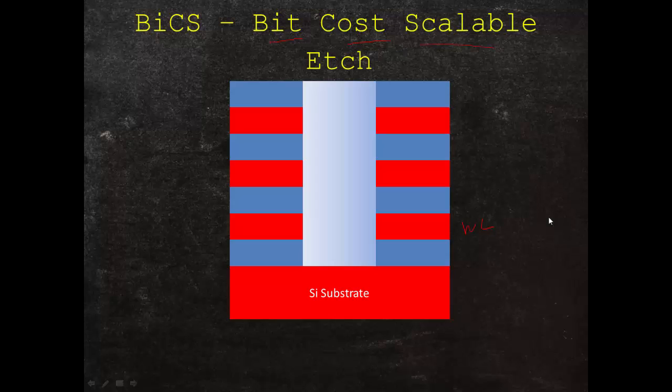So a process note: these are long trenches and they're difficult to manufacture. But only one mask is needed to produce this entire array of holes, and that brings the litho cost down. So we have a pro and a con right there. So the floating gate channel is next, and that's to deposit a silicon dioxide on the walls of the hole, and that makes the dielectric.